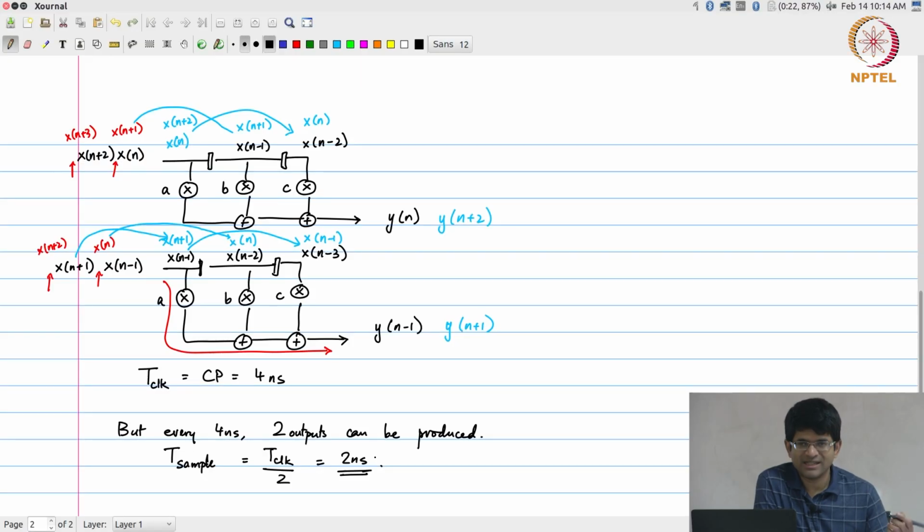So, parallelism in other words is a fairly simple way of improving the throughput, which applies in the case of these kind of especially the FIR filter type of structure, right. There is one additional twist to this that I will just mention before we move on to another approach that can be used to improve throughput, which is slightly more interesting in general.